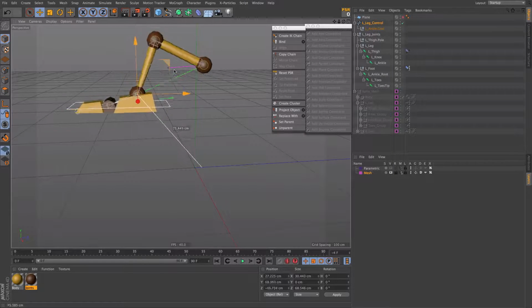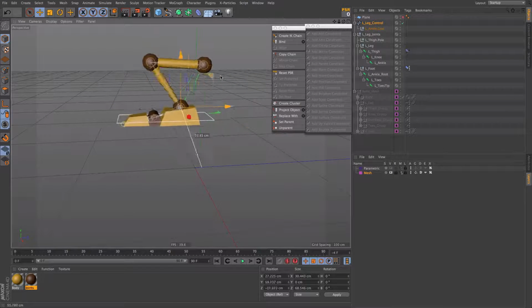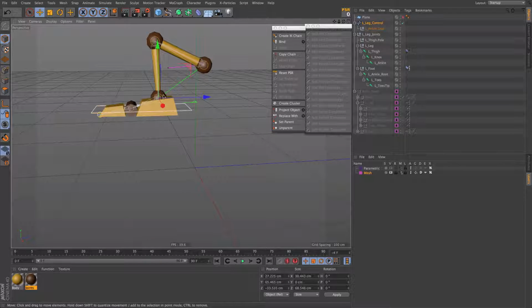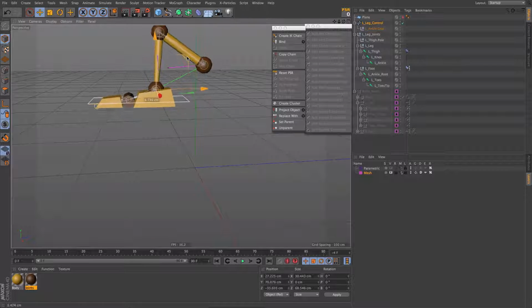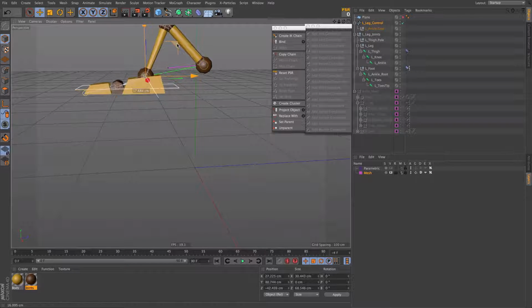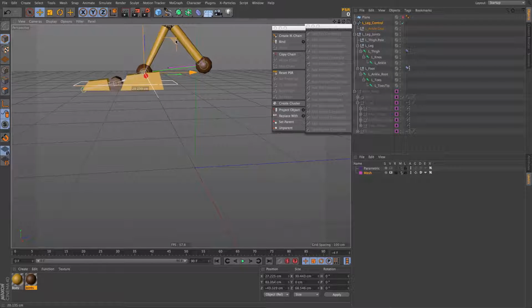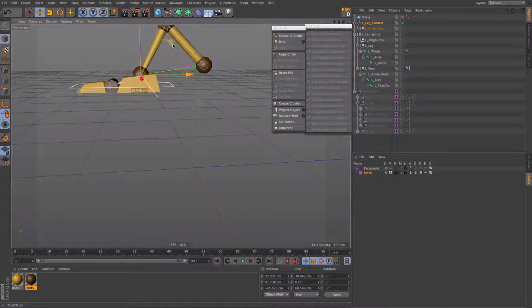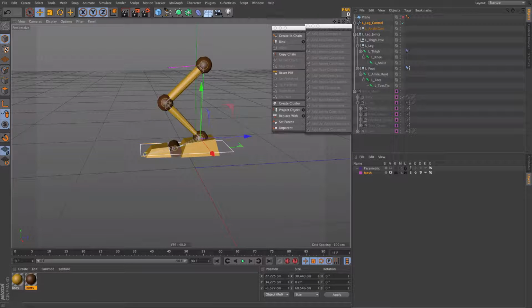So basically we made our first rig. We can see now some weirdness which is happening. You see this line over here, that is from the IK expression, and when this line will move above the pole vector, well, my joint chain is going to rotate the other way, as you can see. So we don't need to worry about that yet.